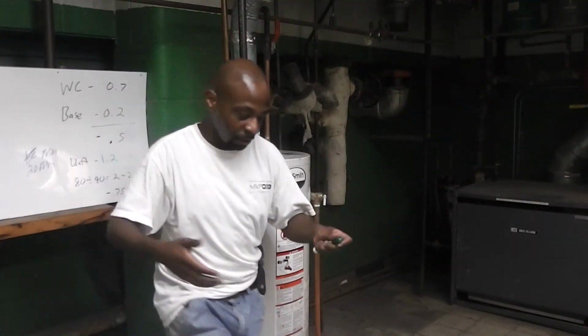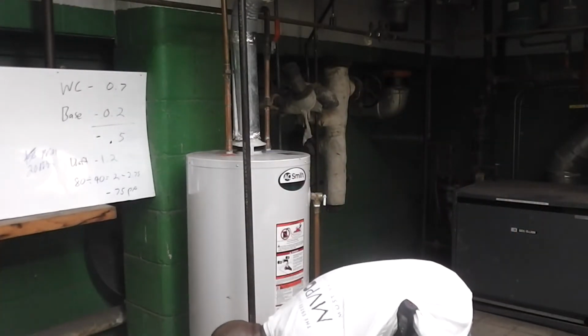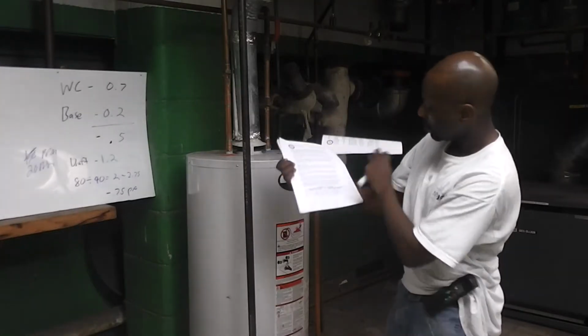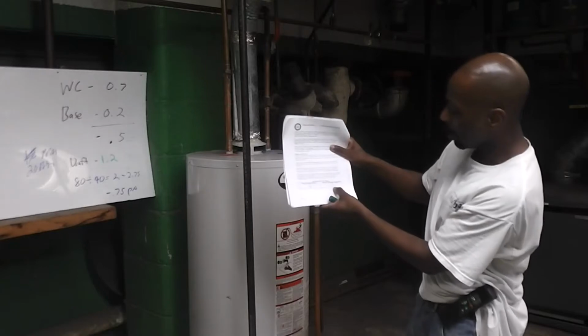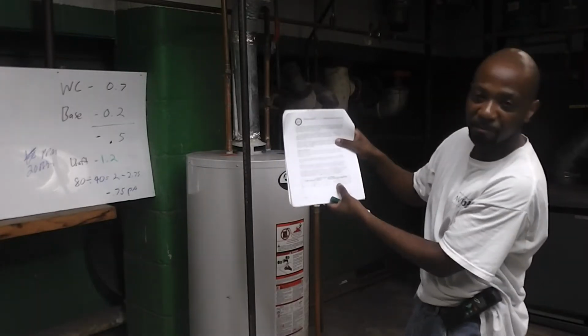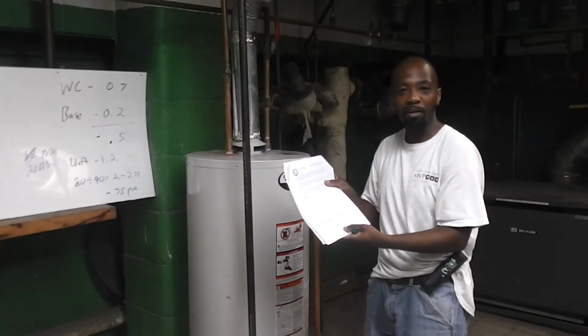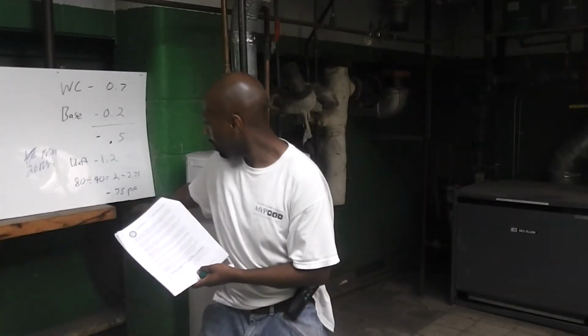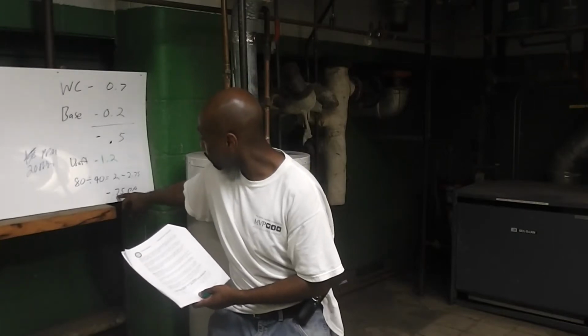So once again, how I know that's good, how I know that's bad, I refer to my chart. Now remember the chart. Let me grab that. So remember the chart had this formula, right? The temperature outside, that by 40 is the same exact chart we use for this. Now we've already done this equation, you already know the number we're looking for. The number we're looking for, if you remember back to here, was -0.75. This combustion appliance inside the flue pipe gave us a 1.2. So 1.2 is more negative than our requirement of -0.75.